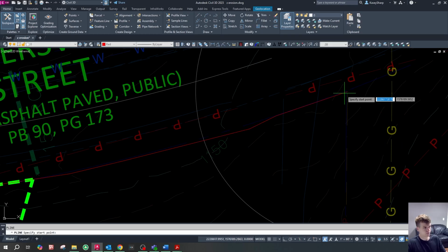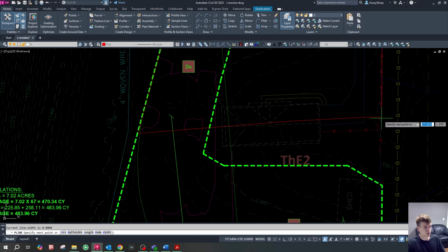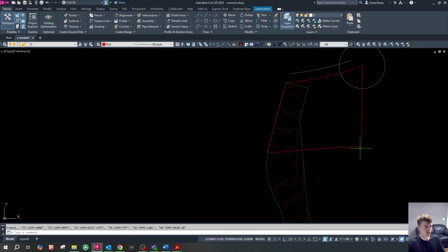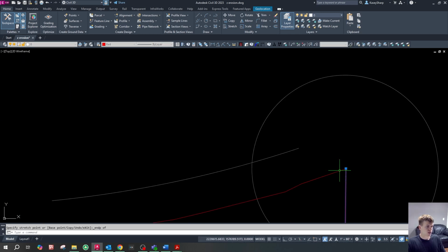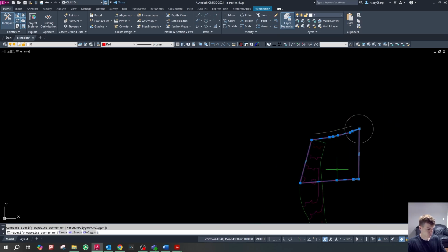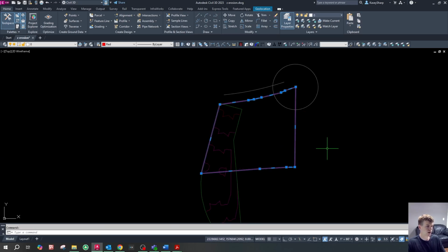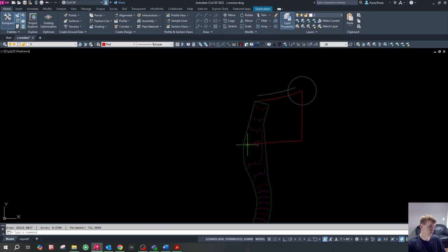Alright. All the way down to here. And I'm going to isolate this guy. And then we're going to connect it so we can find the area. So I'm going to grab this. So this entire northern basin, if you will, that's draining up to the temporary sediment trap we're going to have here is 0.67 acres, so it's less than an acre. So we can effectively claim that we're getting all of the sediment storage from silt fence, which is probably what we're going to try and do.